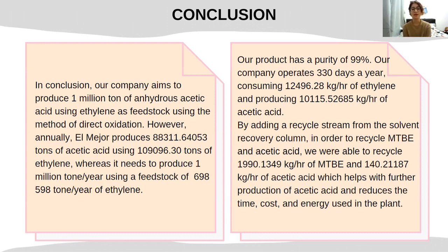By adding a recycle stream from the solvent recovery column in order to recycle MTBE and acetic acid, we were able to recycle 1,990.1349 kg per hour of MTBE and 140.21187 kg per hour of acetic acid, which helps with further production of acetic acid and reduces the time, cost, and energy used in our plant.